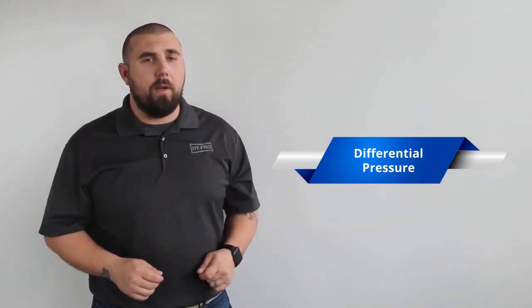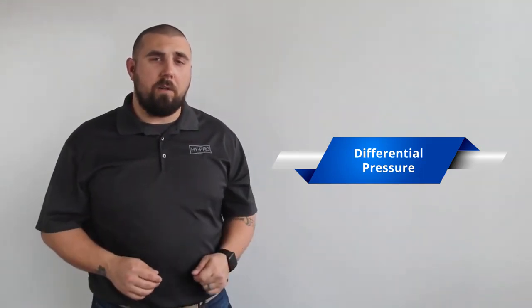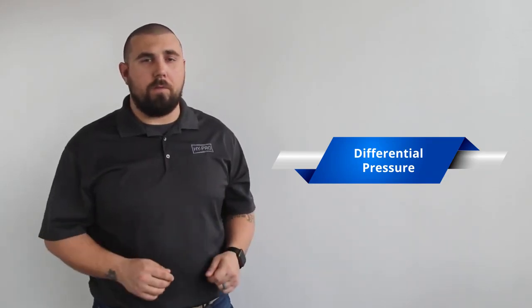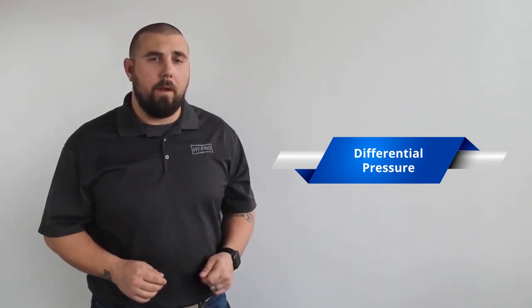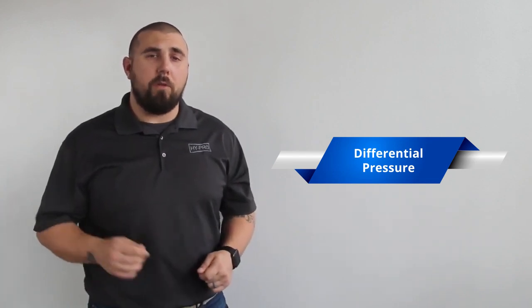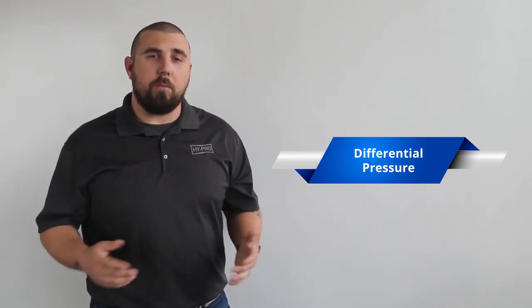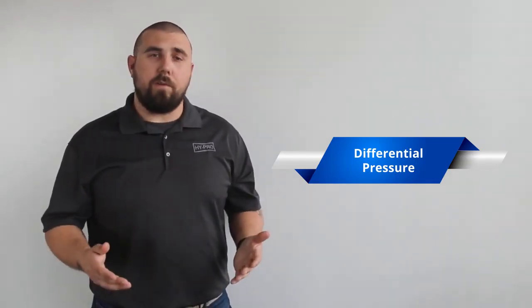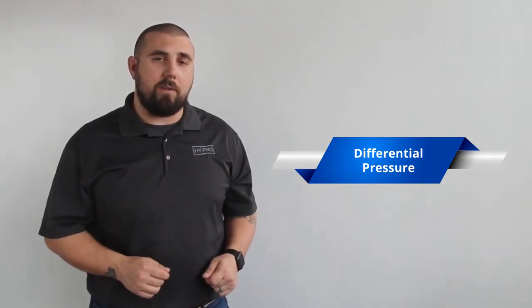Other terms that might be associated would include clean differential pressure, which refers to a newly installed filter's starting differential pressure; operating differential pressure, which refers to the changing of differential pressure throughout the life of the filter; and terminal differential pressure, which refers to the differential pressure limit at which the filter is at capacity and must be changed.